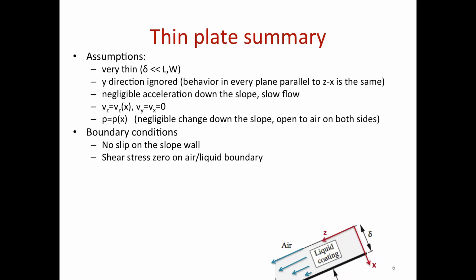That comes from continuity of shear stress across this boundary. And since I have air and liquid, presumably air is much, much less viscous than this is, often an order or even 2 orders of magnitude difference. Because of that, when I have mu multiplying my partial derivative in velocity, that mu will cancel out whatever I have, so that's what's creating 0 shear stress on one side, and because of the continuity, I have to have that on the other side as well.